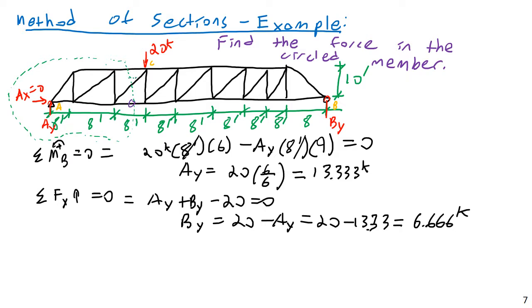Now, interestingly enough, what is going to be cut out is our applied point force here. And that's actually not going to appear anywhere on my free body diagram for my section. So this is kind of interesting. I do like using this section because it illustrates that when we cut something out, we only have to look at the forces that are in that section.